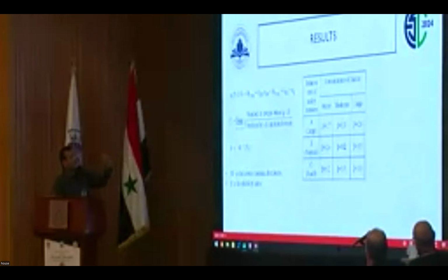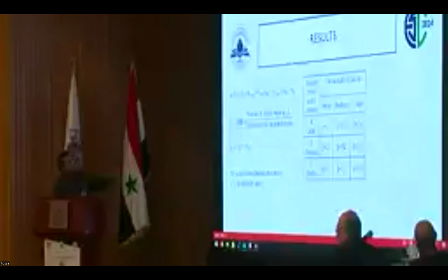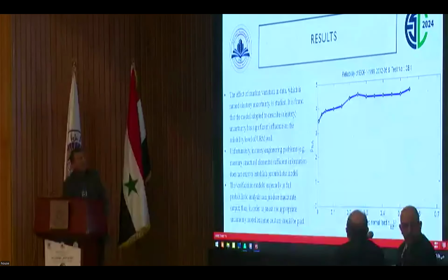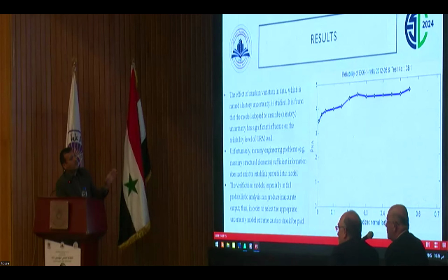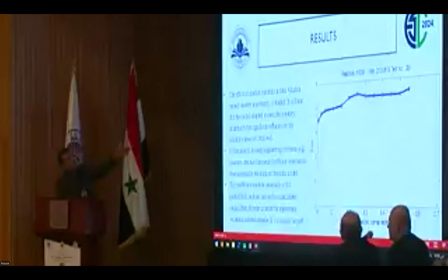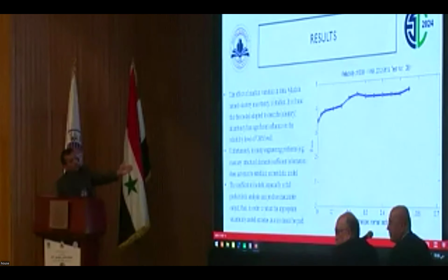Index should be for a shear wall. I took this table from Eurocode. For example, we expected 3.2 for the average reliability index. In this case, we observed that the reliability index is much higher than what we expect, sometimes even more than 4, related to the load.